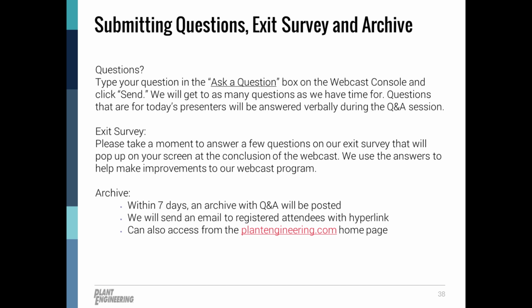Thank you. Ronnie, how does one properly use a megger? Okay, on that question, a megger is a specific brand name for an insulation resistance tester. So there is a standard that's in place, that's the IEEE 43 standard, that's put in place to allow you to know how much DC voltage to apply to the winding, depending on the rated winding voltage. And there are a few different steps that an insulation resistance tester can take.